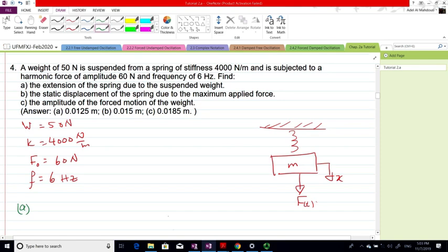So you have to make the free body diagram of the system. This is the mass, right? The mass is pulled down by its weight, okay, and there is a spring force, which is Fs, right? We don't have any normal force in here because it's not landing on a foundation, okay?